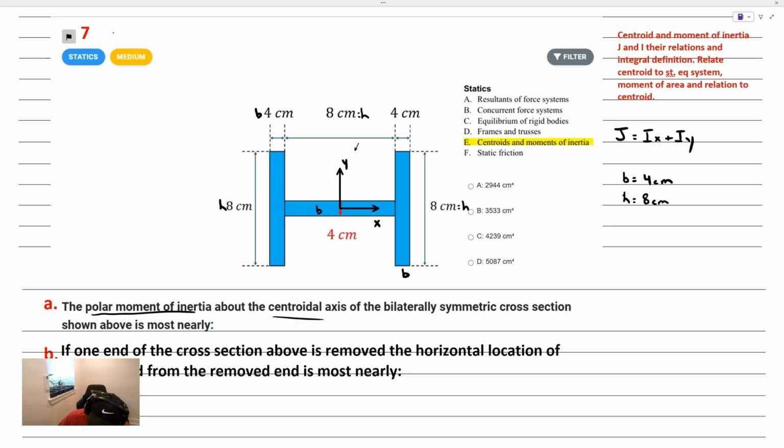Okay, so firstly, let's start off with the moment of inertia about the x-axis. I picked it to start off with because that would never involve the parallel axis term. You could see that if we mark off the centroid of each of these three bodies, they all intersect the x-axis. Because all of these bodies have no distance to the centroidal x-axis, we can just sum all of their moments of inertia.